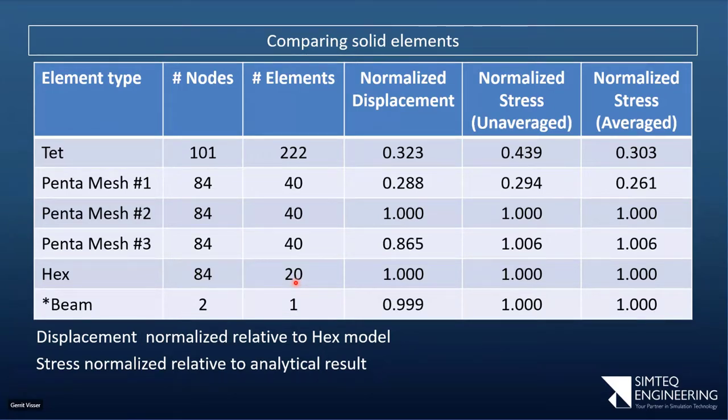So while both of those comments are true, both of those, TET and the tri element, actually start so much worse than the quad and the X that I don't think you ever reach the point where you get a better answer unless you get to the point where those elements start being so distorted that they become inside out.